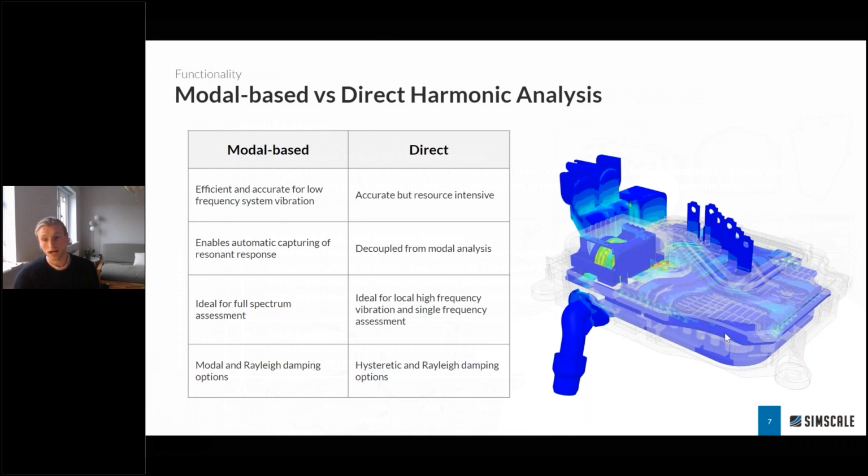So this is great because, even for a large mesh size and a very complex model, it allows us to be very efficient once we have done the modal analysis. We only need to run the modal analysis once, and then we can do harmonic analysis based on those mode shapes. So this makes it efficient and accurate for low frequency system vibration.